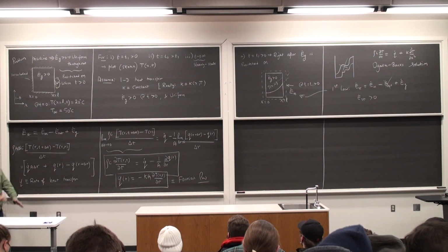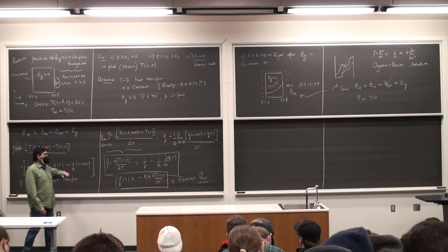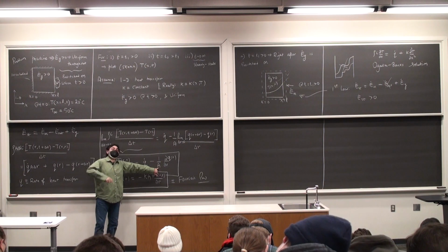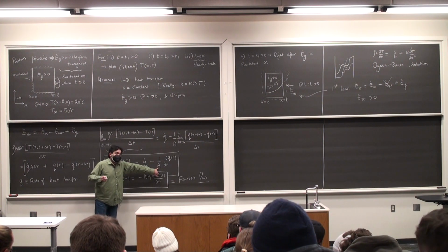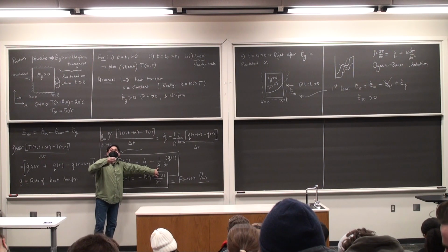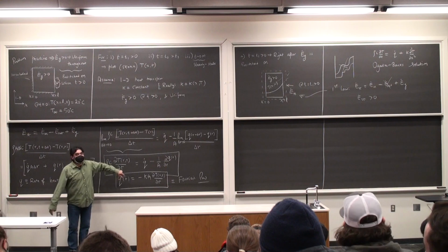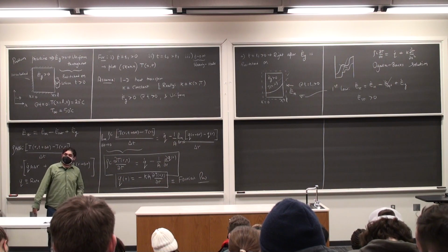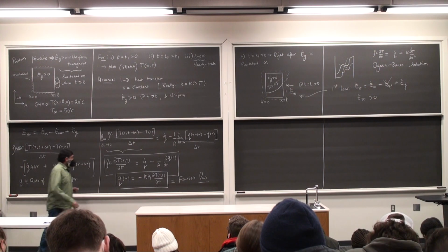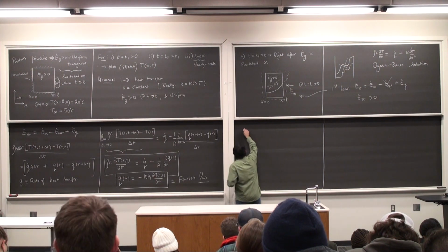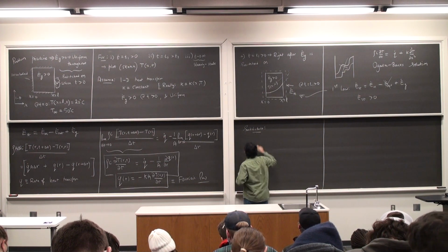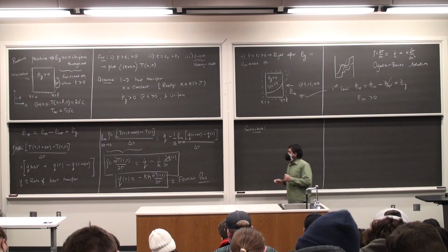Which means you are now going to do the substitution. So be careful, in the plane wall situation, I did not have an area term coming into play. I looked at only the conductive flux terms. Reason being, the area is constant. The area for heat transfer in a plane wall is always constant. That's not the case anymore, because the area is a function of the radius r. So now we are going to do the following. Substitute for Q of R, don't get rid of the area yet.